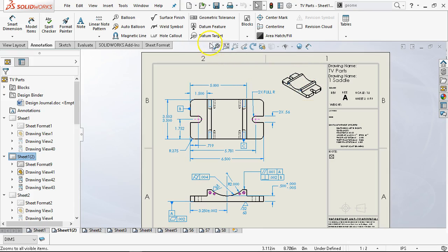Okay, so we'll work a little bit. I think I'll try to build out some more of the dimensions on this. For these parts and what this is doing, anything that is a jig or fixture, so a jig holds the tool, a fixture holds the part as a general reference, anything that becomes a jig or a fixture typically needs an order of magnitude above what you would do for the normal tolerances of the part.